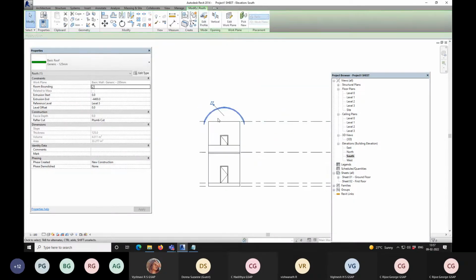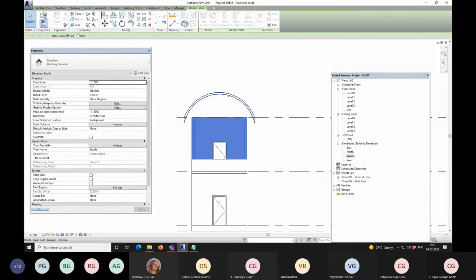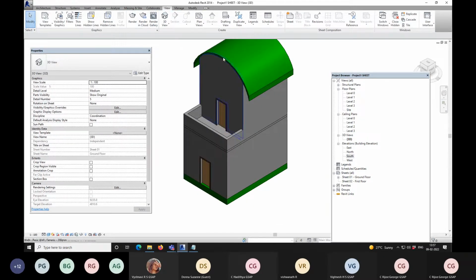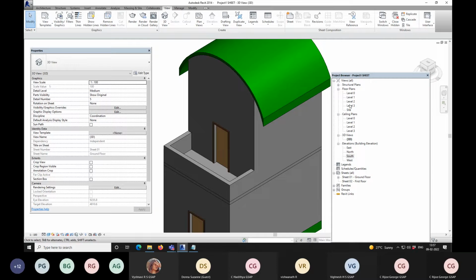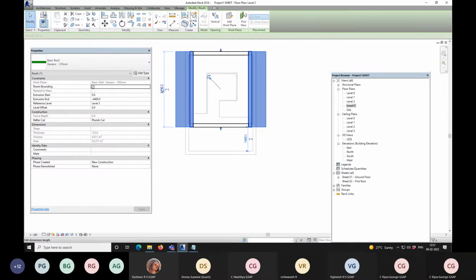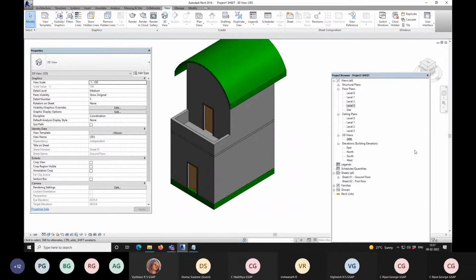And you can also select very quickly, attach top base, select like this. So in 3D, you find that it has come till here. So in level 3, it is stuck to this wall, 4,400, make it 5,600, sorry. So it extended 200 that side and 200 this side. So job is done.